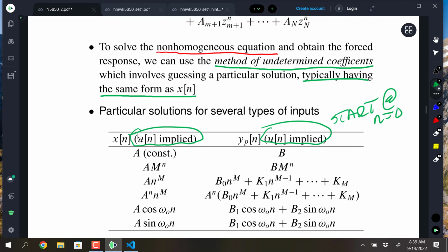Just mentally thinking, if we're going to get anything out of a system when we drive it with a step, what does that system have to have in terms of its responses? It has to have a DC, a non-zero gain, in order to support a constant going in and producing a constant coming out. And we're going to see shortly that B will be A times the DC gain of the system, because that's just logical. Now, does engineering typically not defy logic?